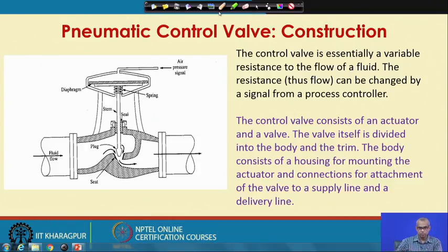So, as the air pressure signal increases, the pressure on the valve top increases. That pushes the diaphragm downwards, so the stem goes downward.